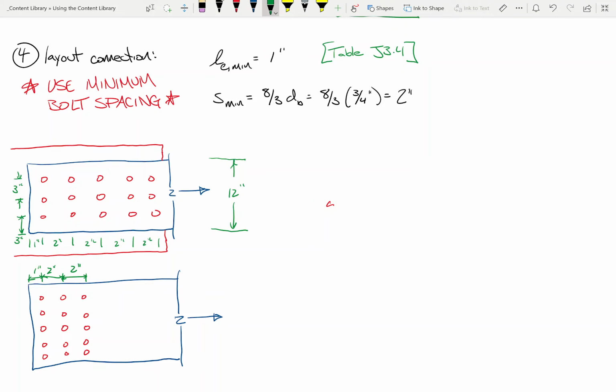Okay. Now, before we start figuring out dimensions this way, the reason I brought up the whole corrosion and wrenches and all that is the following, okay? Does the connection meet bolt spacing and edge distance requirements this way? I would say yes. But a follow-up question, does the connection have to meet bolt spacing and edge distance requirements this way? Does it have to? Well, do we still have a corrosion problem this way? Do we still have a getting-a-wrench-around-the-bolts problem this way?